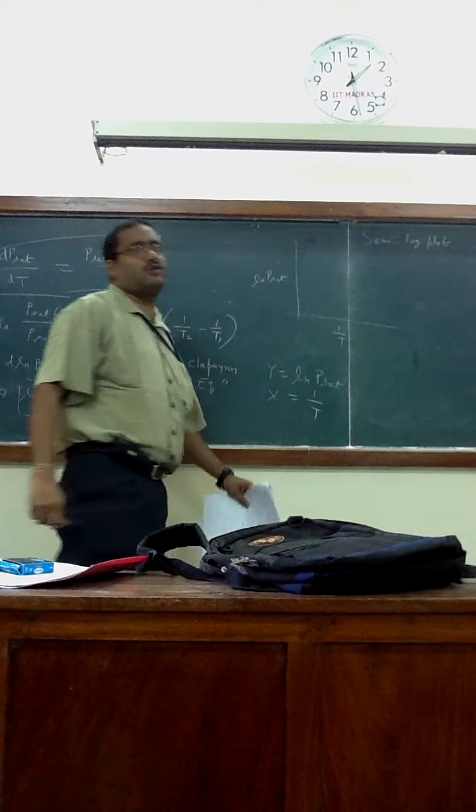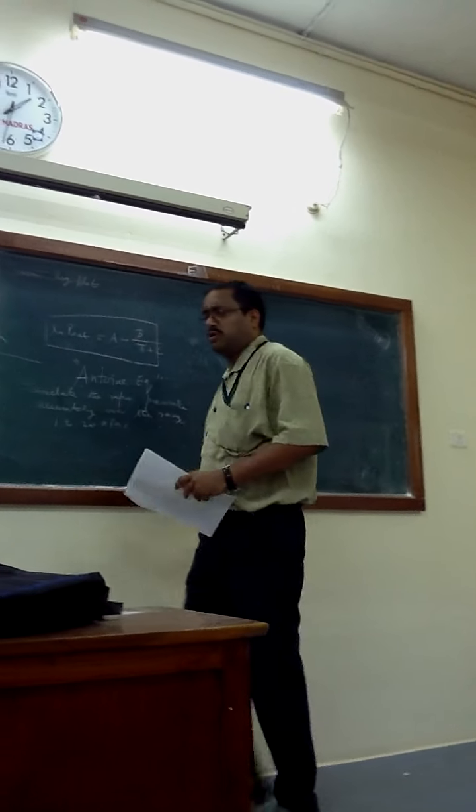The point is, as I said, how low? They are saying up to 200 kilopascal you can use it. Beyond that, this may diverge, because the entire foundation of the proof of this equation is based on the fact that the system pressure is pretty low, and they are saying that up to 200 kilopascal it is fine. So further corrections have been made by Riedel and like the Brown equation. So Riedel gave a correction.